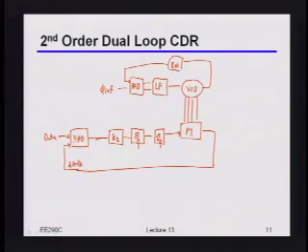Okay, so now, if I'm really building the equivalent of a PLL, or actually just in general, will what I just drew here work, or will this have a problem? Yeah, it's unstable, right? I just put two integrations in the loop with no stabilization, no zero, nothing, right? So how do I add the zero in?